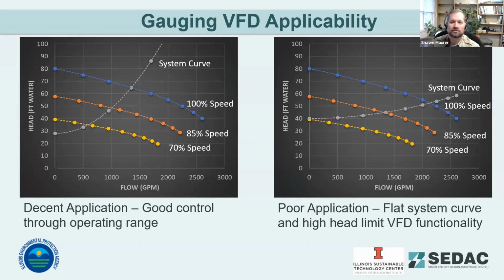Would a motor over 10 horsepower that runs over 2,000 hours a year be a good candidate for VFDs? I think it would be a good candidate depending on what the load is, but if it's going to run continuously, a lot of times you only need all that power at original startup. So once you get the pump running and the fluid is moving and you get rid of that original static from turning it on, I think that's always a great item to turn it down. Even just a little bit over time creates major savings.